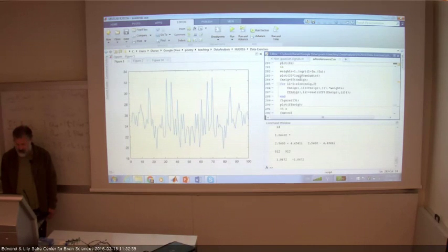And I'm calculating here. So in the script, I think you have 10, when I plot the weights, they should be plotted on a logarithmic scale, but in order to get the right dB for calculation of filters, they need to be plotted as 20 log 10. Because the weights are weights of amplitudes. So they need to be 20 log 10.